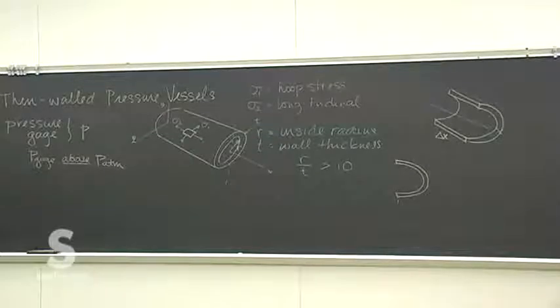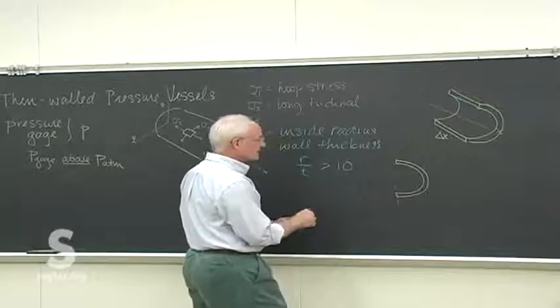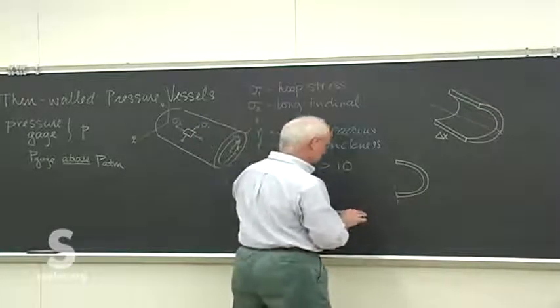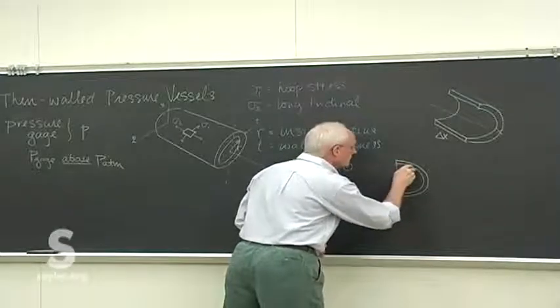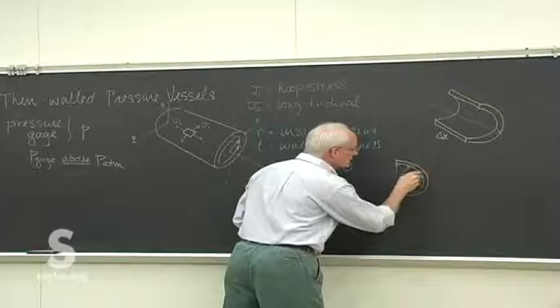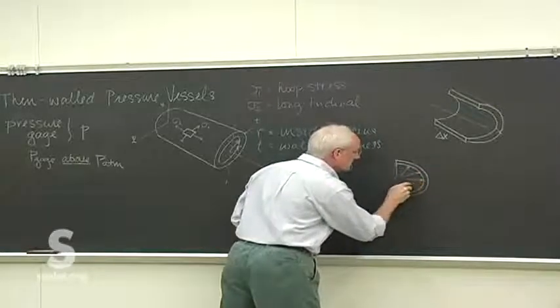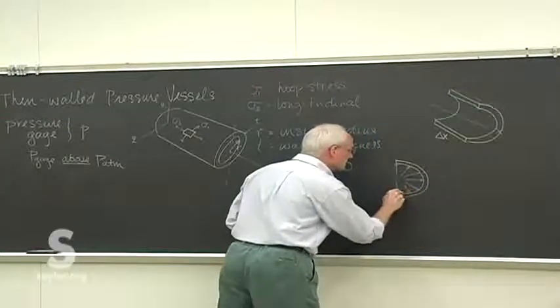What I'm looking at is the hydrostatic pressure, the pressure of a fluid on a solid surface. And in this case, we have a curved surface. Now, it might seem problematic at first because the pressure is a force that can act normally to a surface only. There's no transverse ability of pressure to exert any forces.